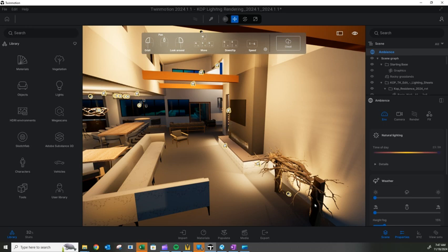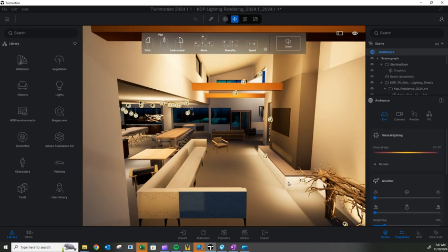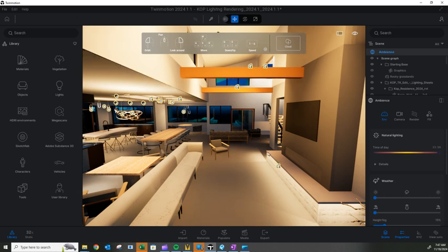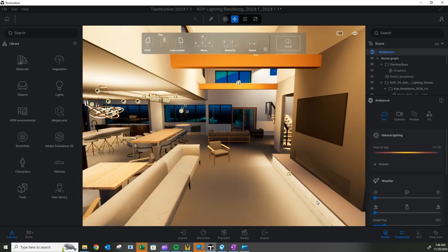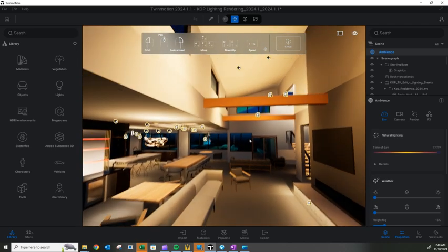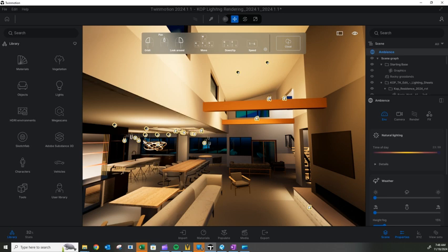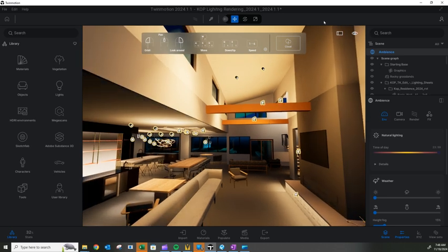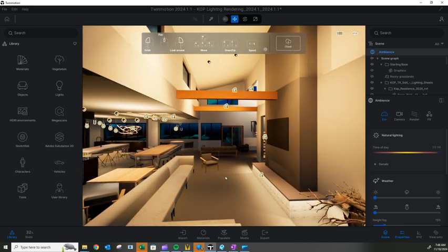A lot of what we do is called layering, where we layer in the light. Like over here, we have two in-ground lights that are casting a low ambient uplight to create shadows and draw attention to this little wood bench the client's going to have. It doesn't look exactly like that, but we just drew that up there for an idea so they can see what it would look like. And then underneath this seating area, underneath the concrete seating, we have tape light to cast an underglow. So just within the space, we have one, down light, two, up light for the art, three, the decorative light, four, this underglow, 5 layers of light already.